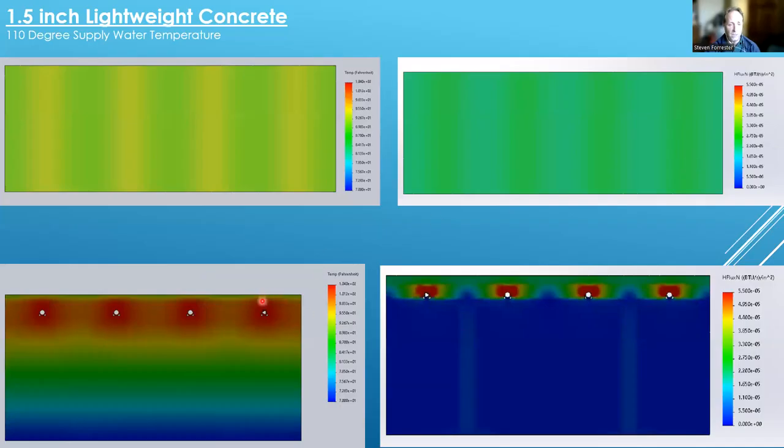However, you can see the energy is trapped within the floor system. Again, this is why I'd call it a high mass system. It's not going to want to change temperature fast. There's a lot of heat trapped within the floor system. You can see very localized energy within the concrete, so it's all trapped right here and here, being put out to get to that floor system.